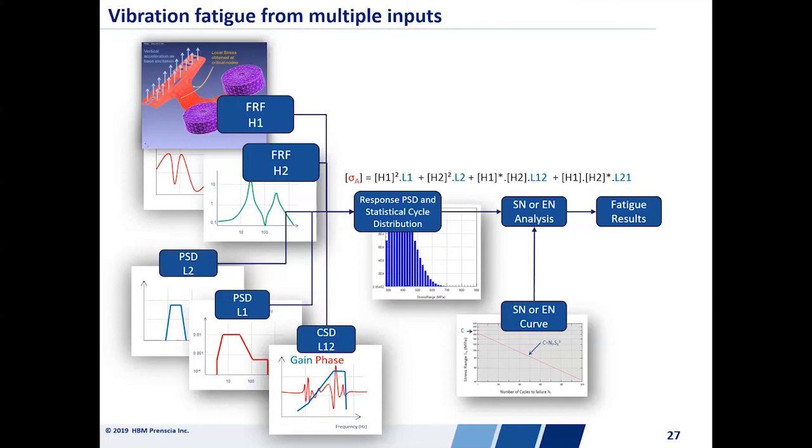What we see here are some sample plots of phase and gain, and essentially what that is suggesting is at any given frequency, and let's just say at a specific frequency like 20 hertz, when we have an excitation in the X, what is the gain of that excitation for the Y, and also what is the phase? Are the two both occurring in a positive direction together, or are they out of phase and essentially might be oscillating back and forth out of phase of one another?